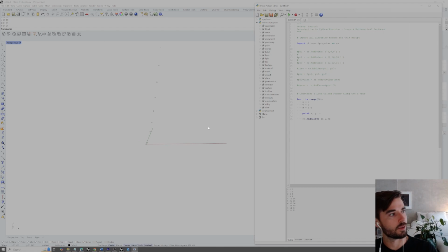And if we didn't have that in the Y, what would happen is we would draw just a straight line directly between the midpoint of both of these axes, and our Z would curve up. So if we hit play, we can see that exponential curve as it steps up. And we can see that go from 0, 0, 0, and then 1, 1, 1. And then since we're performing that square, the X and Y are just stepping by 1, but now we step by the square value of whatever our I value is for our Z. So 4, 9, 16, 25, and so on.